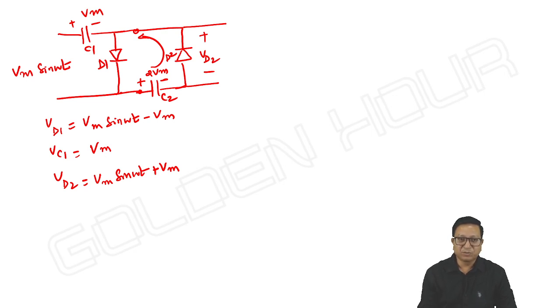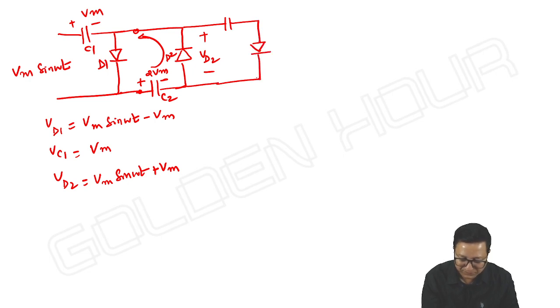Now, whose output is given as input to again another negative clamper. Negative clamper means this one. You see this combination, right? It is a negative clamper. So, to what level will the capacitor charge? The capacitor will charge up to the positive peak of the input signal.